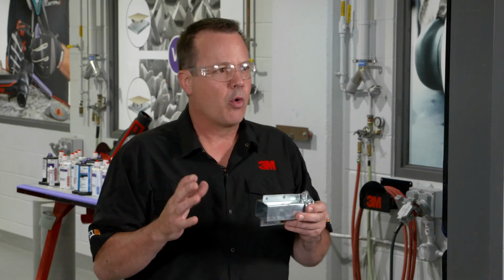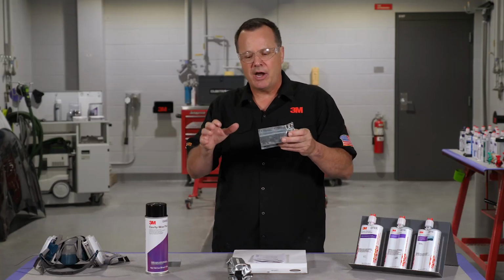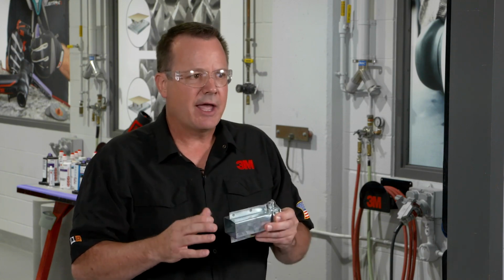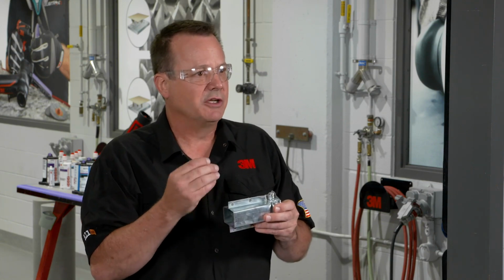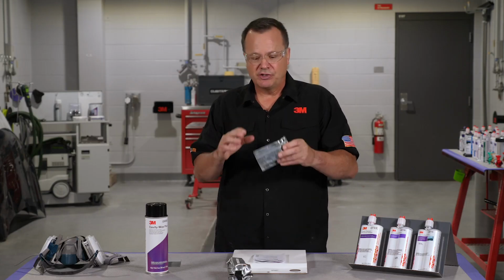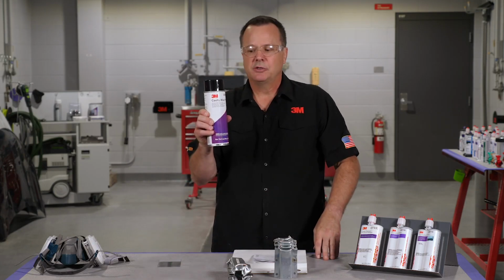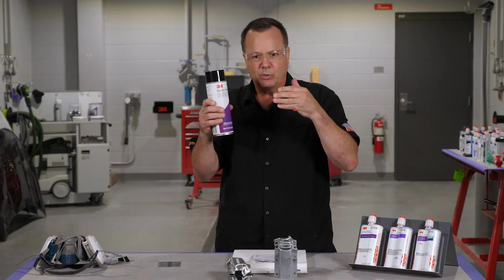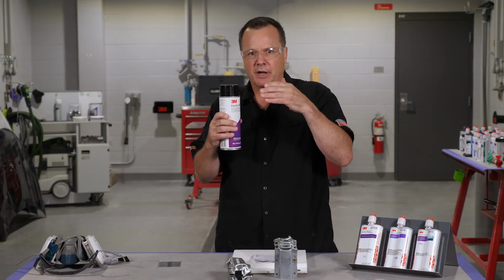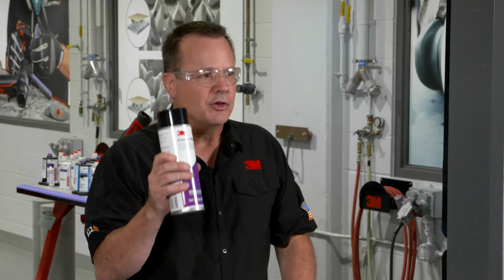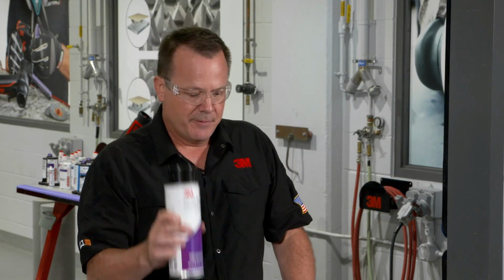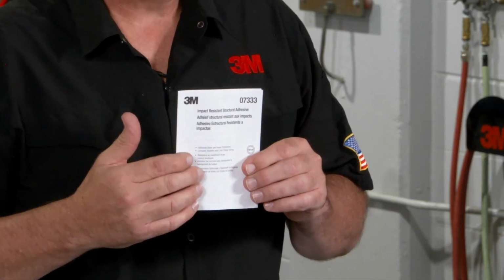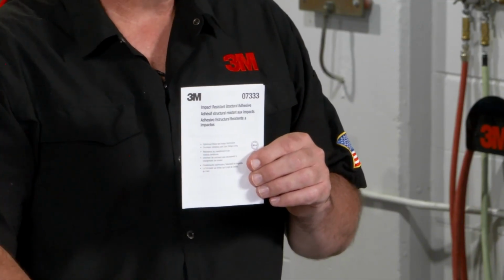A great example of that are quarter panels. When you hang a quarter panel, oftentimes you need to force it a little bit down onto that wheel arch area. And in the process of that, it is possible we could scrape some of that adhesive off and leave a void. So insurance against that would be Cavity Wax Plus. So as long as we follow all bonding operations with Cavity Wax Plus, which will get into those areas that might be exposed and cover them and creep in, you're not going to have that corrosion in those joints. Also, if you read the product sheets, these will tell you always follow all bonding operations with Cavity Wax Plus.